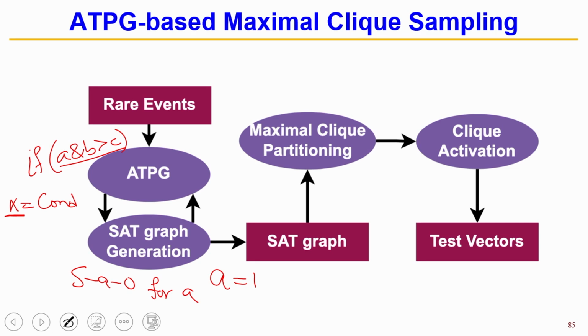and create a stuck at 0 of that variable x. So, you have to instrument the design, which does not change the functionality of the design, and then we have a stuck at 0 on that element. That is what we ask the ATPG tool: do a stuck at 0 on that. Then ATPG will give you the solution. Any questions?